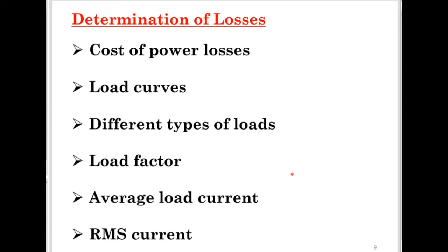So if I put all those loads in the curve, we call it the annual load curve, meaning it's showing the power generation or the power consumption curve for a year. So we have the daily load curve and the annual load curve, but we also can have one in between, meaning a monthly load curve. We want to show the loads for a certain month for 30 days, day 1 to day 30. So that will be the monthly load curve.